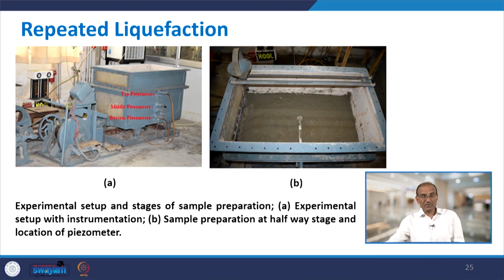So, for the experiments, the table which has been used, which we call the liquefaction table, or simply people call this vibration table also. This is a one dimensional table, which is kind of a tank. Inside the tank you can put your sample, let us say Sonali sand in this case, and this sample has been soaked for saturation for quite some time until all the water goes inside the voids, and then the extra water from the top is removed before any experiment is conducted. So, it is basically a saturated sample of the soil.